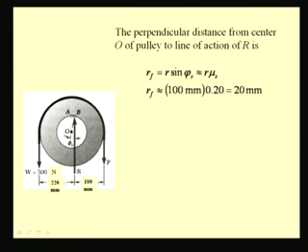So, for the particular case we find this as 20 mm. So, the reaction R is shifted by 20 mm to the right from O. So, we have these distances as 200 minus 20, which is 180 mm, and this distance between this vertical force W and R is 200 plus radius of friction, which is 220 mm.